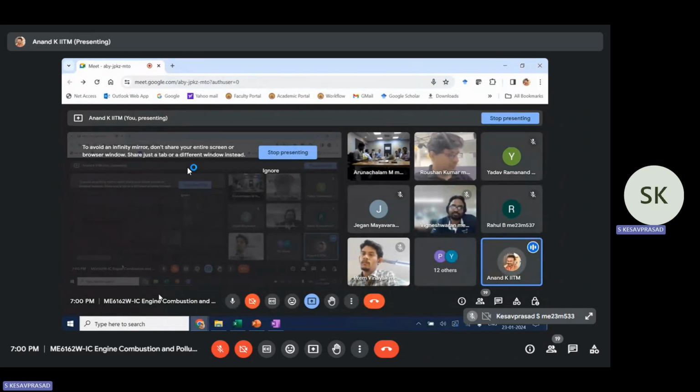About your question on catalyst, there are a lot of ignition improver additives. Suppose you have a very poor ignition quality fuel, you have to use some additive, an ignition improver additive. One of the most widely used additives is EHN, ethyl hexyl nitrate, which is an ignition improver additive. It will reduce or shorten the delay time to avoid engine damage.